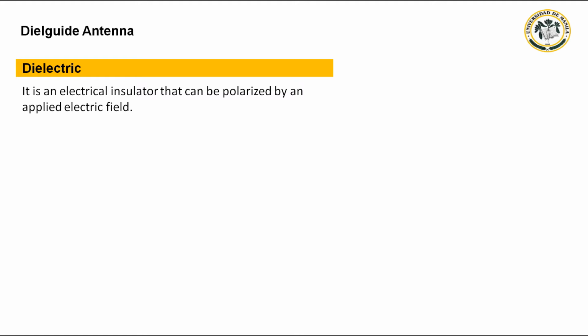The presence of the dielectric material affects other electrical phenomena. The force between two electric charges in a dielectric medium is less than it would be in a vacuum, while the quantity of energy stored in an electric field per unit volume of a dielectric medium is greater. The capacitance of a capacitor filled with a dielectric is greater than it would be in a vacuum. The effects of a dielectric on electrical phenomena are described on a large or microscopic scale by employing such concepts as dielectric constant, permittivity, and dielectric polarization.